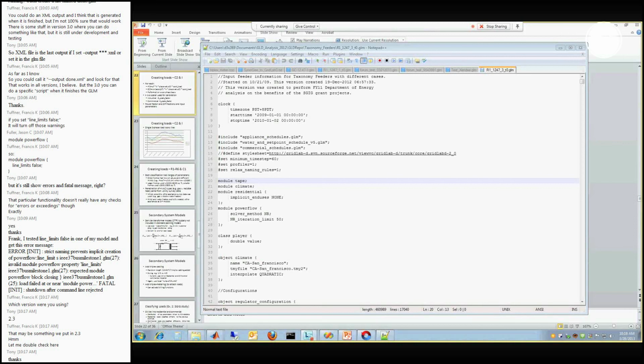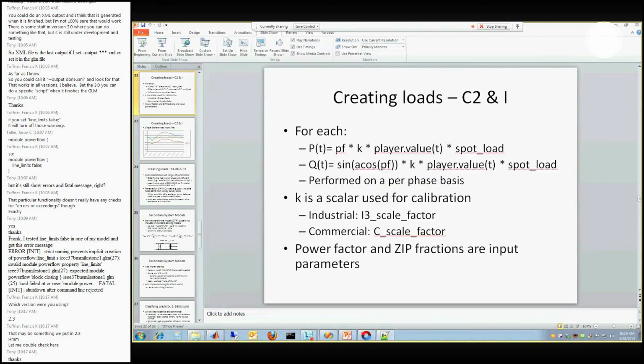The other thing I would like to do, but I don't know if we'll fit it into our timelines and our funding, is right now the reliability module will give you a version of the IEEE 1366 metrics. Of course, it's built off of the old GridLAB-D framework where you're doing 1 second or larger time steps, so some of the things like recloser actions you don't quite capture right. I'd like to at least get the quote-unquote delta mode or the transient functionality into reliability, so in the future we could expand that, or if somebody in the community wanted to, it would be allowed, but I don't know if we're going to get to that this year or not.